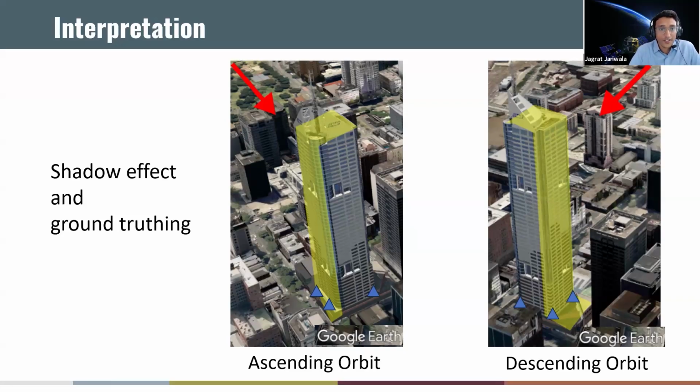The recommendation here is to convert your movement estimates from conventional systems, such as your survey control points or your GPS points, and project them to the line of sight axis and compare those to understand how good or how accurate your InSAR estimates are.